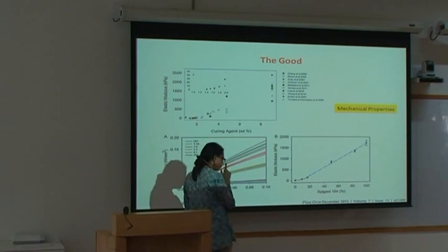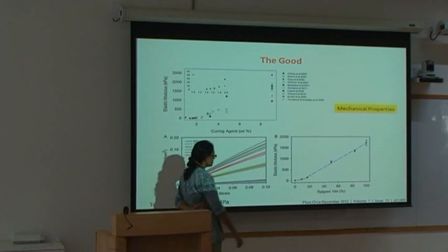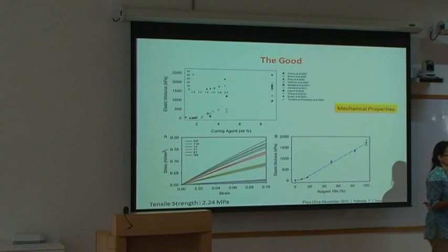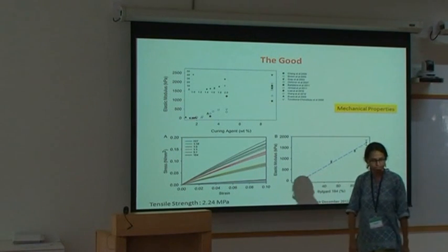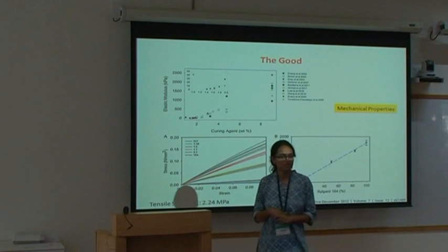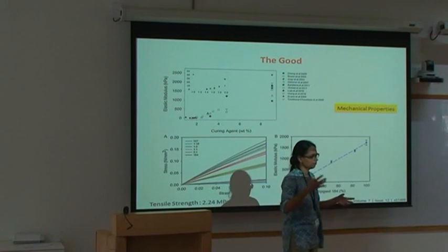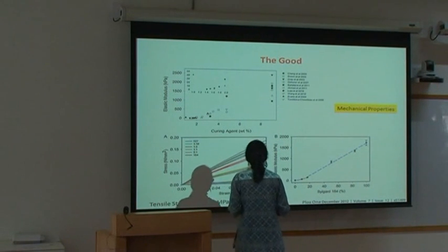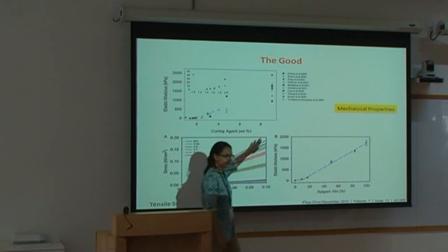One thing to remark here, which I may not come back to, is that assigning a stiffness to this polymer only works when you are working in ranges less than 10% of stretch. If you remember when we worked yesterday, we went 20, 30, 50, almost 80, we crossed 80. We discussed if the stiffness actually changes with doing this, and Dyke's talk yesterday in a different context showed that if you stretch something, it can change. So it's good to remember about PDMS that these numbers are for below 10% stretch. That's the linear regime, after which it becomes non-linear.